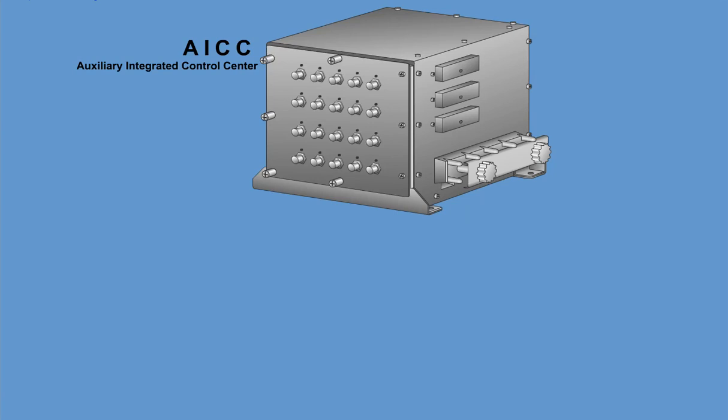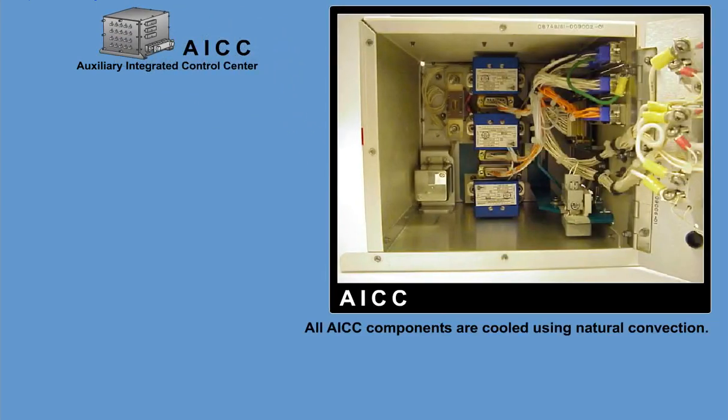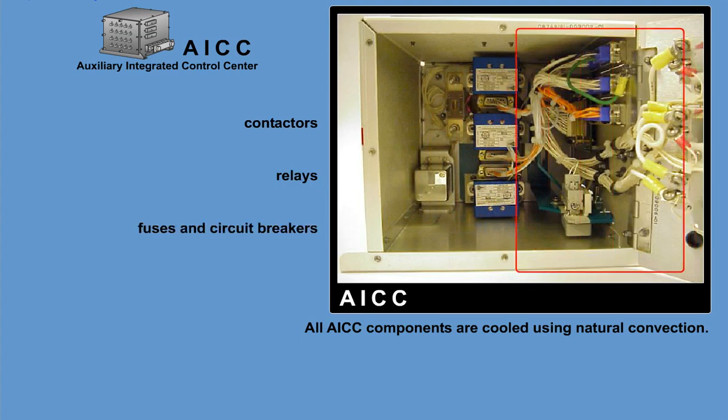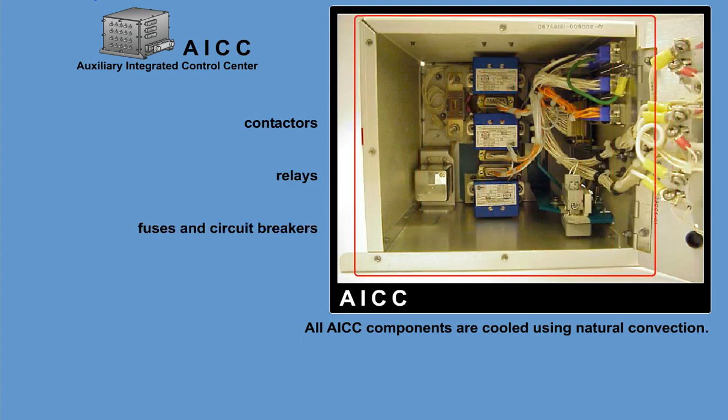The AICCs are mounted and bonded using 4 fasteners through the 4 mounting feet. All AICC components are cooled using natural convection. All normal maintenance for removal and replacement of the contactors, relays, fuses, and circuit breakers is performed through the front of the AICC.